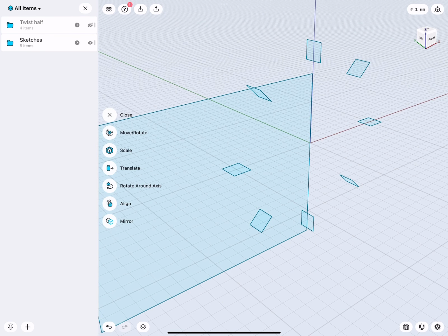So the problem I mentioned is when we want to do this twist, in real life it is just a band which I twist and then weld together, but here in CAD we make a 360 complete loop and then try to twist it. And logically, the problem is the endpoints we can't flip.